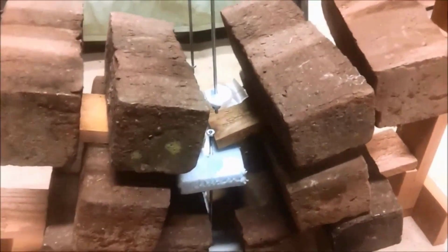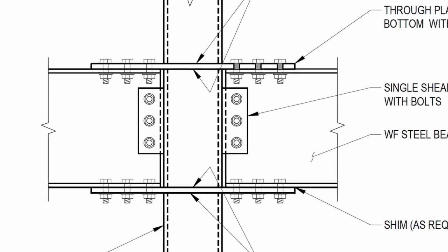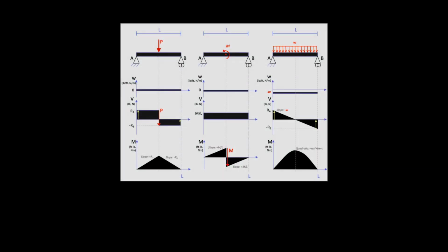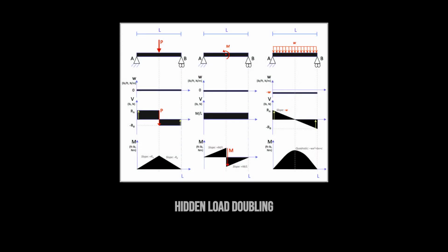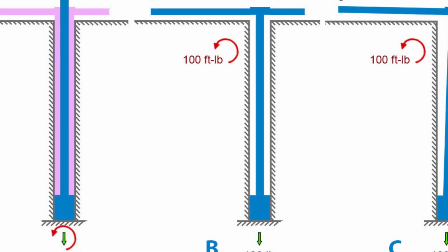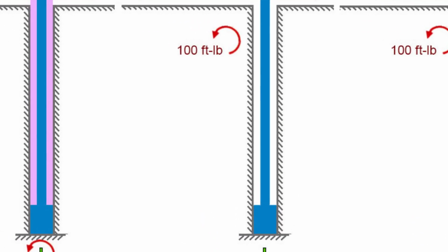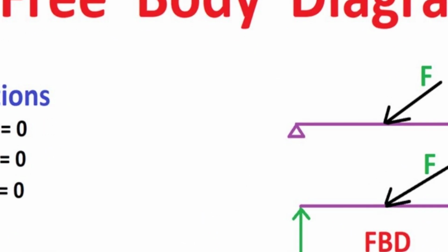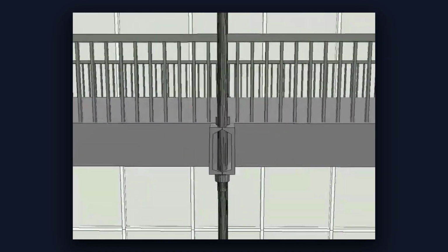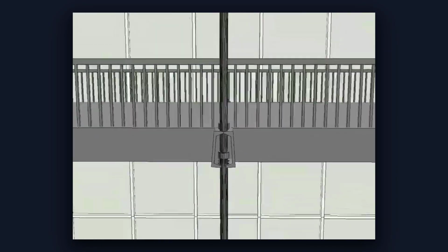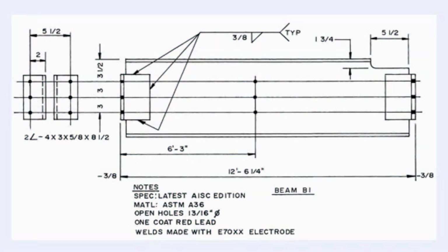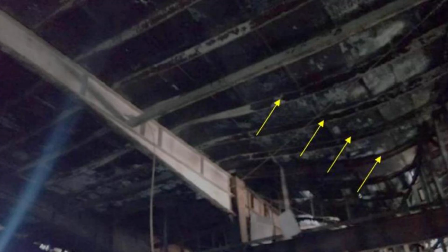The box beam web, never designed for this sum, now had to carry twice the load it was meant to resist. The free body diagram for the connection became simple. The sum of vertical forces equals the upper walkway load plus the lower walkway load. The arithmetic proved the system's new weakness. What looked like a minor fabrication convenience had, in a single step, doubled the demand on a single piece of steel.